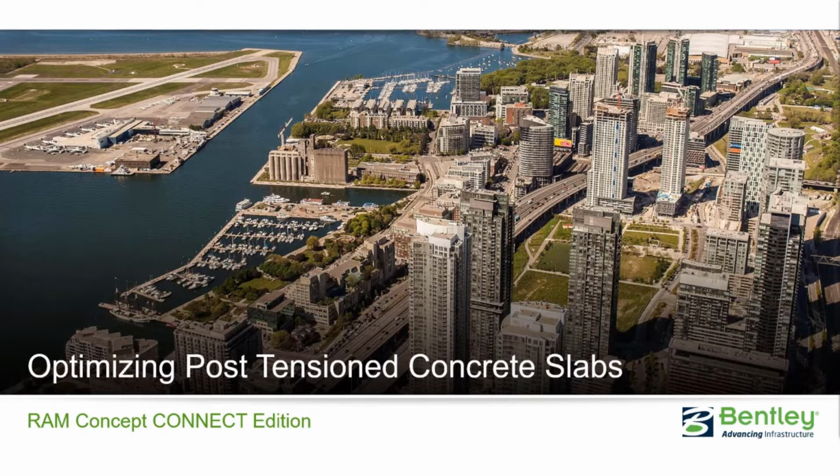and punching shear reinforcement. The post-tensioning optimization workflow in RAM Concept utilizes intelligent search algorithms to compare thousands of design alternatives. This will allow you to easily review and compare many different solutions side by side and select the best design for your situation. The optimization workflow will also weed out invalid trials that do not satisfy required code criteria, which eliminates the need for manual iteration, and it can save hours of engineering time.